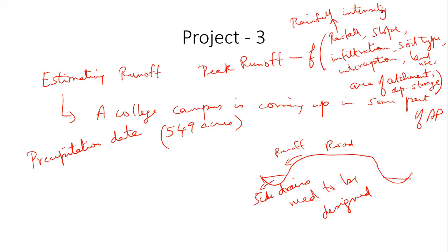See now, remember this. Within your 500 acres or whatever your campus is, you may have different kinds of soil, right? If I have sand in one location, I'll have a longer ponding time. If I have clay in another location, I'll have a shorter ponding time. That does play a role in runoff. I'm not denying that.